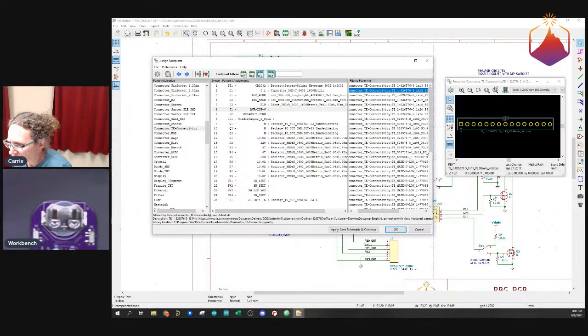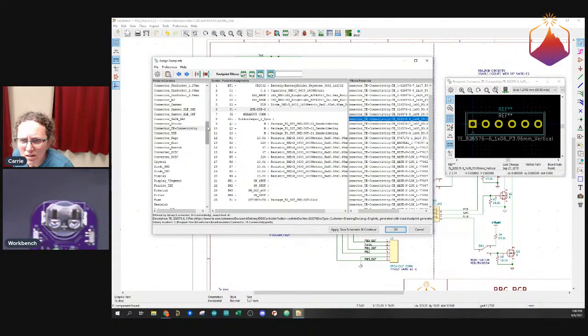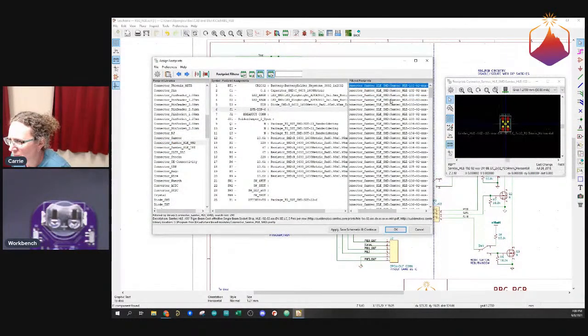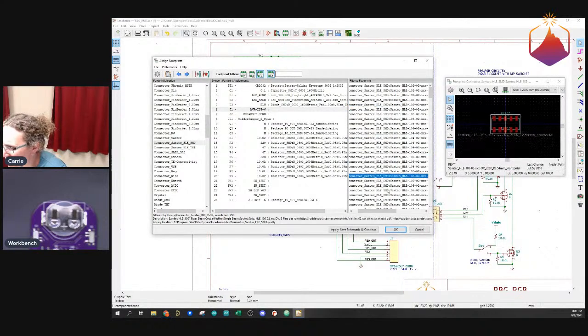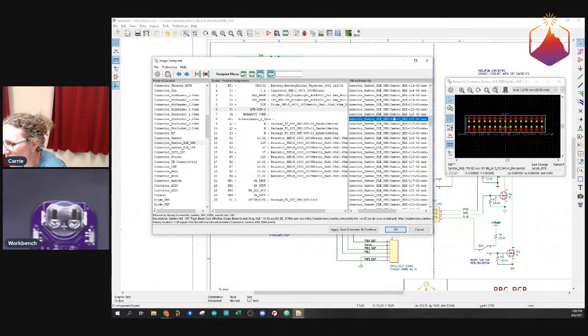1 by 3, 2. It's definitely not like a Mate-N-Lock series. No. Okay. Yeah, I feel like we're going to have to probably, so these are all Samtec surface mount ones, but I think they're all like kind of standard 10th inch or less spacing. Well, this is a standard 10th inch header that is a surface mount version of it.